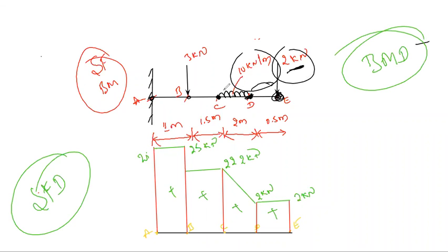Okay. Similarly, you draw the bending moment diagram. Draw the bending moment diagram for this. First, you need to calculate the bending moment at E. Tell me the answer now. Bending moment at E is 0. What is the unit? Kilonewton meter. Force into distance is kilonewton meter.